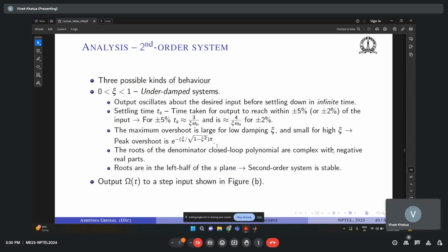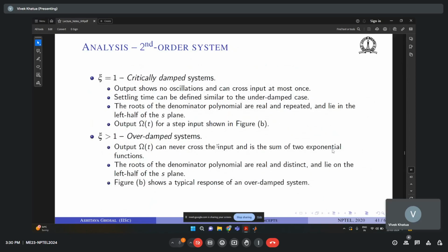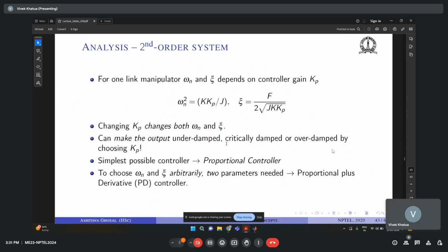Anyway, moving forward, we would introduce something called damping here. So this is for an underdamped system where your epsilon is under 1, and where it's equal to 1, it's critically damped, and for greater than 1, this is back to vibrations. It will be overdamped.